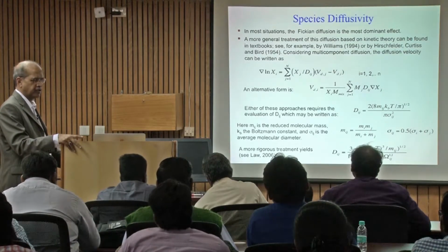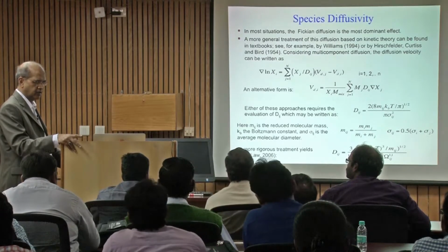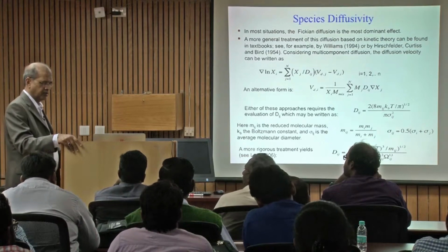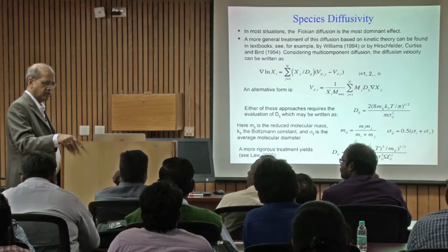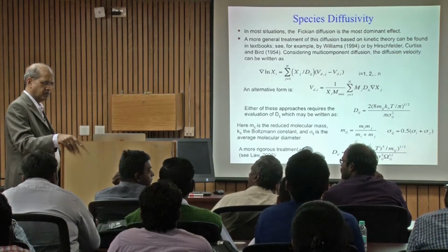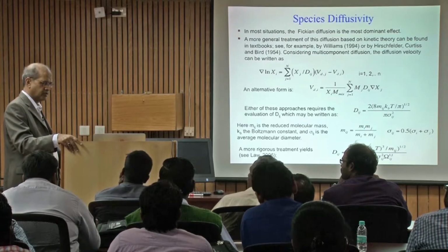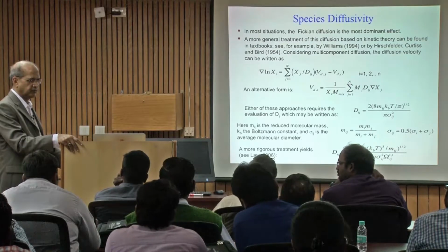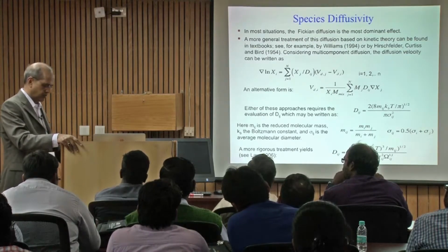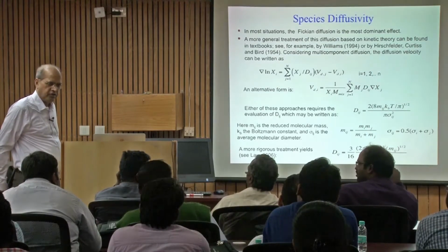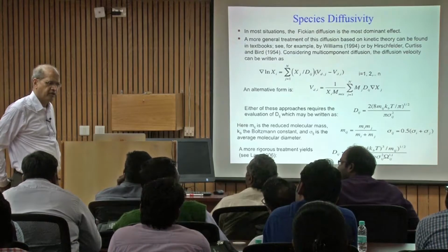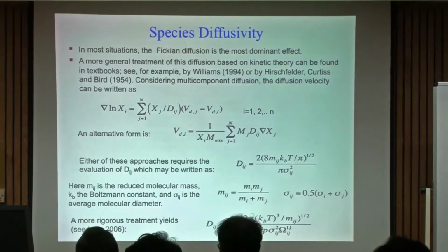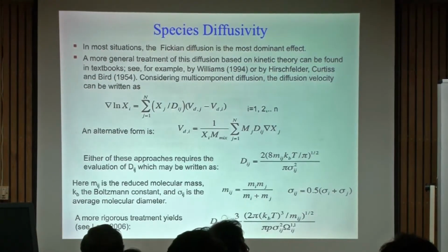Anybody remember the thermal conductivity of gases? Is that T to the power 2? I forgot now. It is 0.026 for air. How does it vary with temperature? Is it T to the power 0.5 or 1.5? Anyway, so here it is T to the power 1.5.